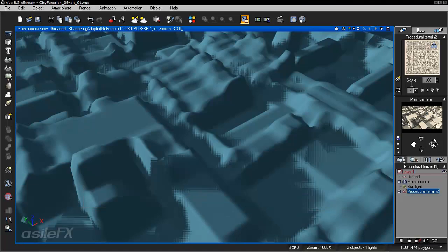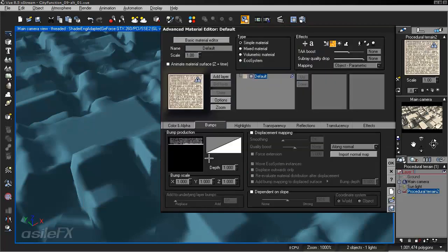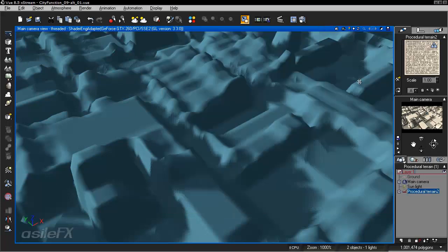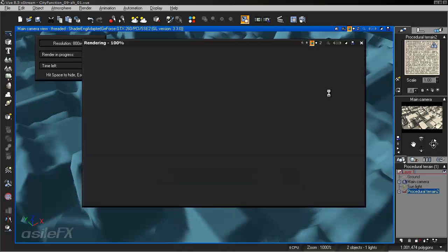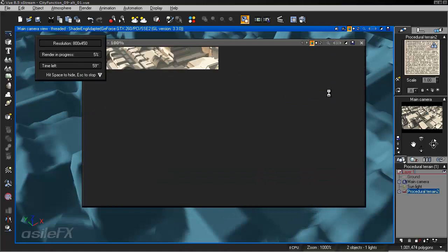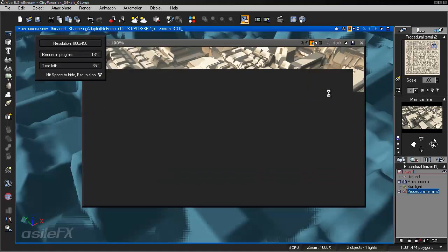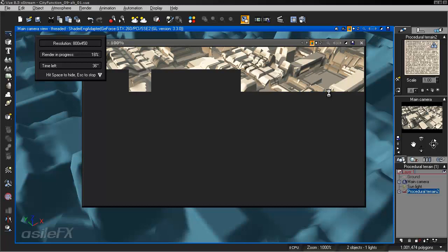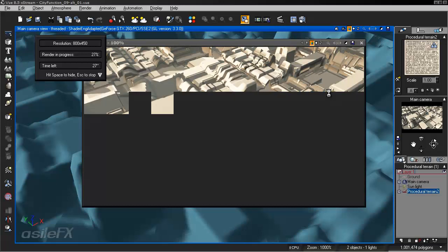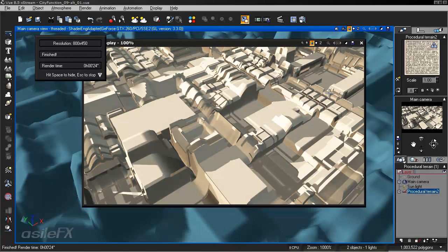Another thing we could do is if we wanted to reverse this, so instead of having an exact extrusion, we can reverse the depth and go to a negative. So let's go ahead and set this to negative 2. So we're reversing the function to subtract rather than add to it, and that can make it look even more impressive depending on the settings that you have. In most cases it looks pretty good. So we're seeing a little more detail now because we're setting it in more.